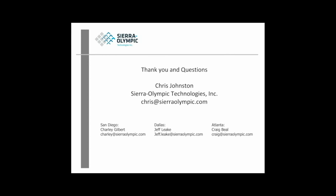How are calibrations for thermography performed with LWIR systems with adjustable optic/focal lengths? Generally, they're not. Most thermographically calibrated systems are with a single field of view. I think if you survey the industry, it would be difficult to find continuous zoom or multi-field of view systems that are thermographically calibrated. And it's a complicated discussion as to why this is.